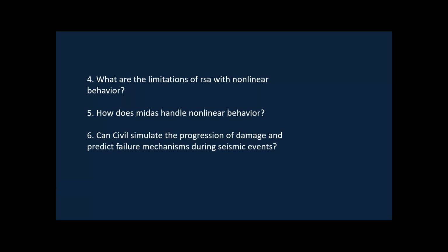Similarly, we do not see any criteria with respect to the ductility of the structure. Strength and ductility are the two most important things that we need to consider during nonlinear analysis. In response spectrum analysis, we try to consider strength somehow, but we nowhere touch the ductility, or we touch the ductility indirectly with the help of the R factor, which is a very indirect approach.